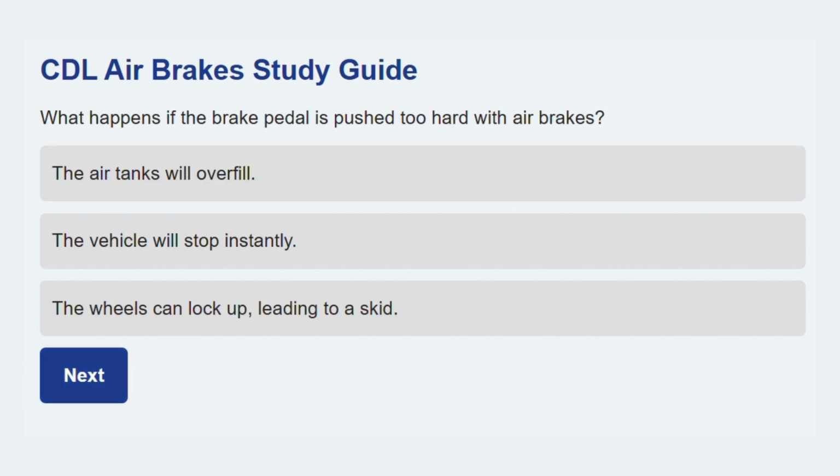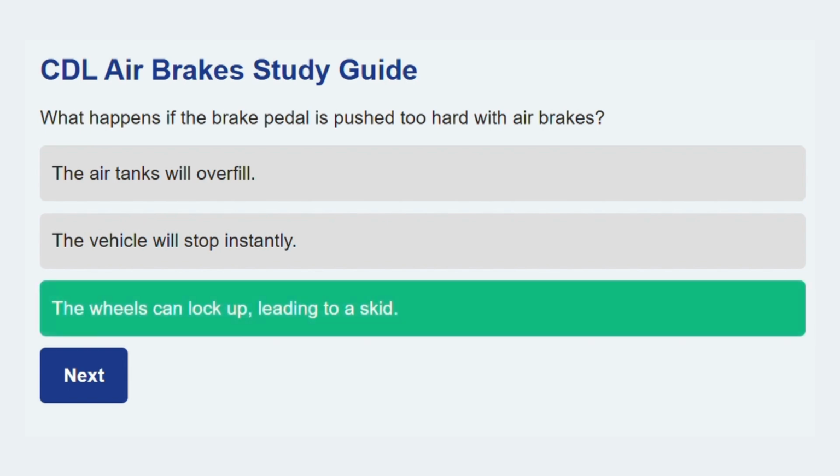Next question. What happens if the brake pedal is pushed too hard with air brakes? The wheels can lock up, leading to a skid. It's crucial to modulate the brake pedal to avoid locking the wheels and losing control.